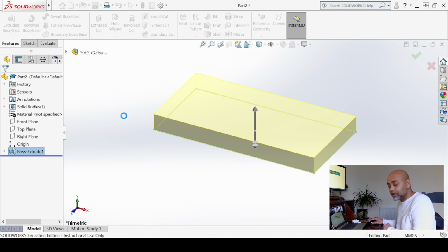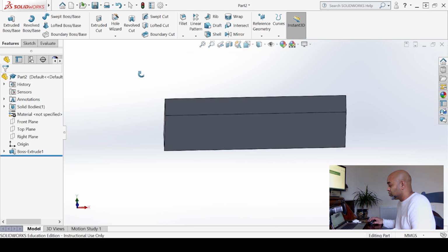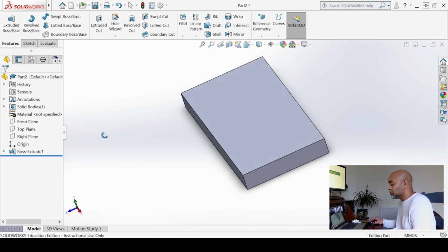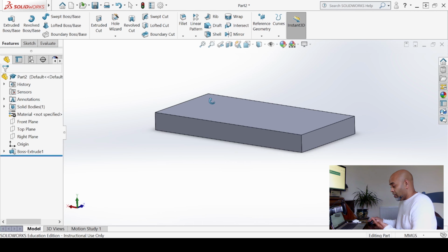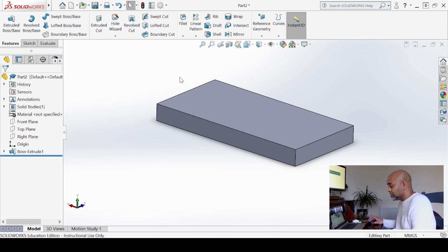And this is how you generate a base profile, a solid. This is your first model that you created now. This is based on some dimensions, 100 by 200, and this is 20 millimeter tall. And then I can use the middle mouse button to be able to take a look around. It just looks beautiful. I wish it was a real piece of cheese.